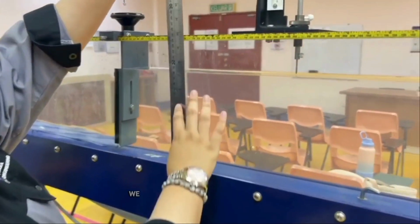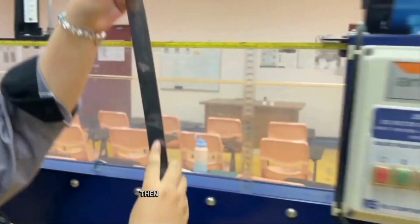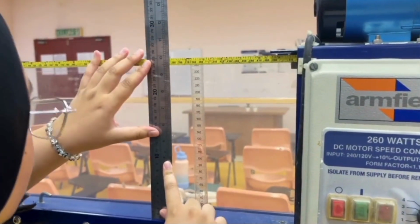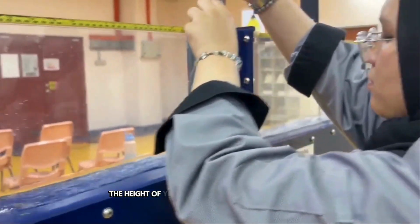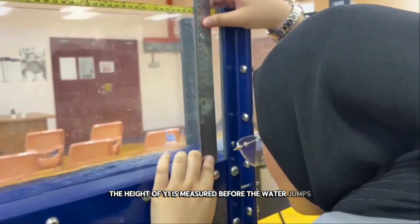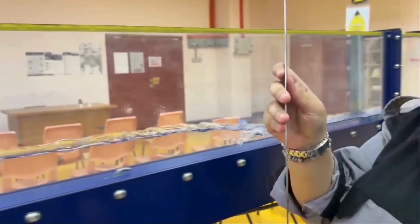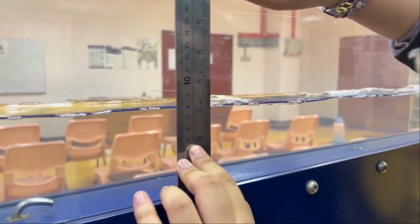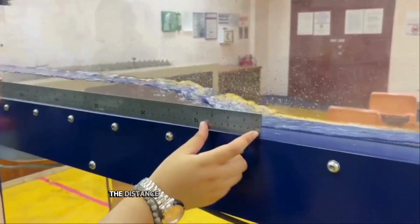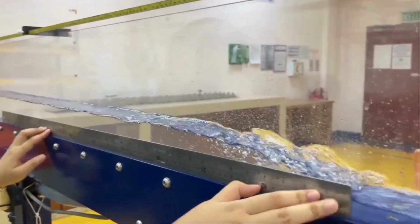After the water is stable, we measure the height of the sluice gate. Then we measure the height of the Y. After that, the height of Y1 is measured before the water jumps. And the height of Y2 after the water jump is also measured. The distance is also measured between water jumps until the water is in a stable state.